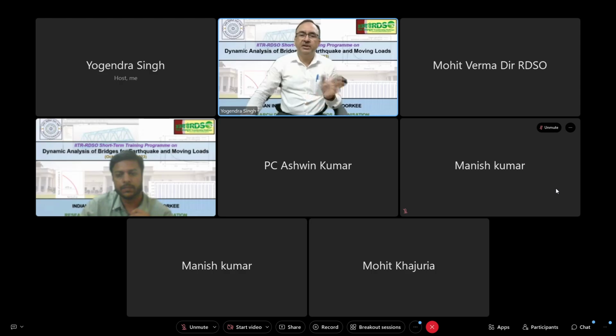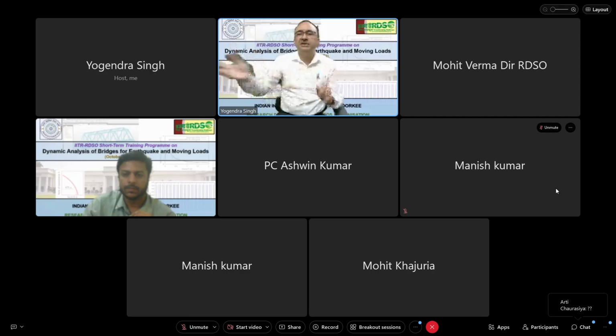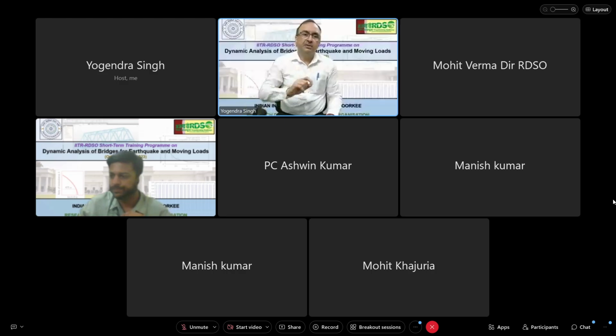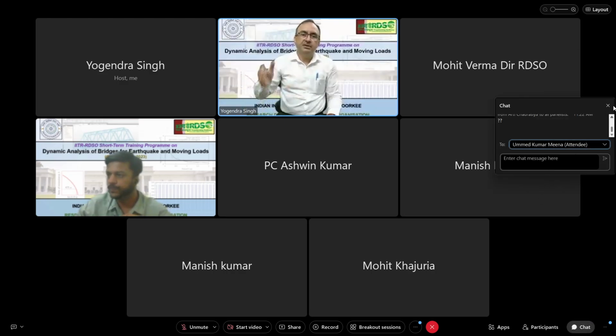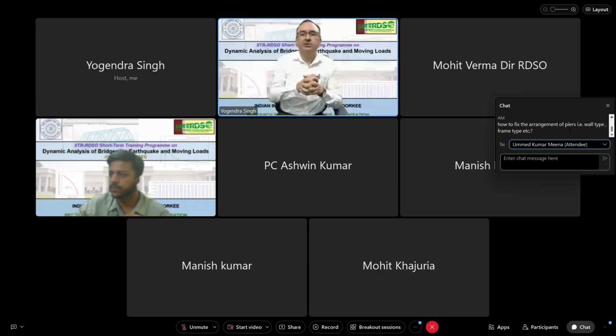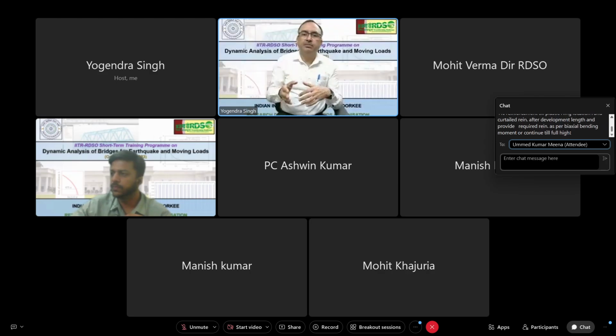What we do in case of an elastic structure, when it yields, its stiffness changes, and stiffness depends on the displacement. Larger the displacement, less will be the stiffness, and this stiffness is defined using secant stiffness. So when we define secant stiffness, we can take into account the variation of the stiffness due to displacement. But we do not know how much displacement will occur prior to analysis.